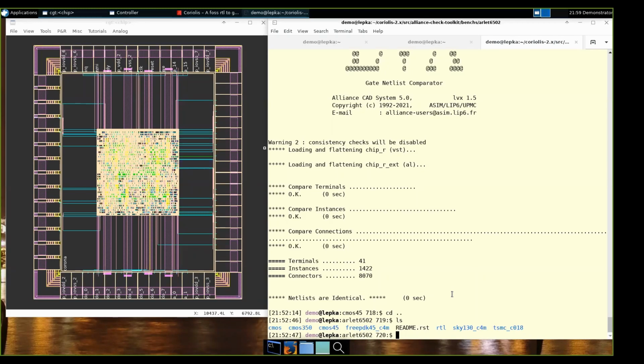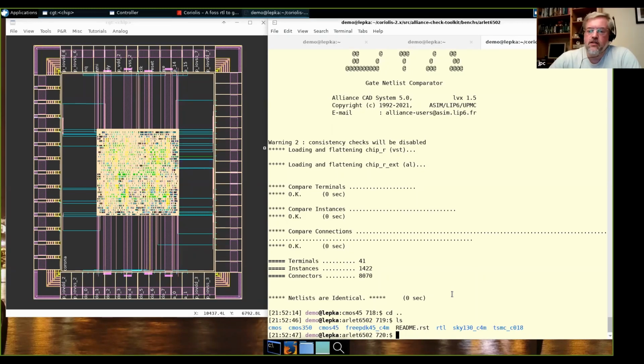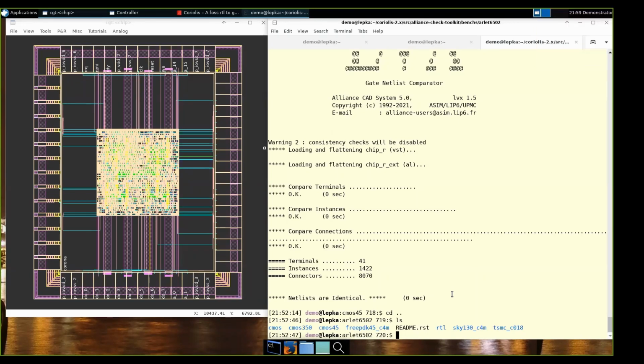Sure, because the tool works exactly the same way. And we have especially configured the FreePDK45 like it was the TSMC one. That is, six layers of metals, and we changed slightly the pitch and so on. I also had to create a couple of fake cells.